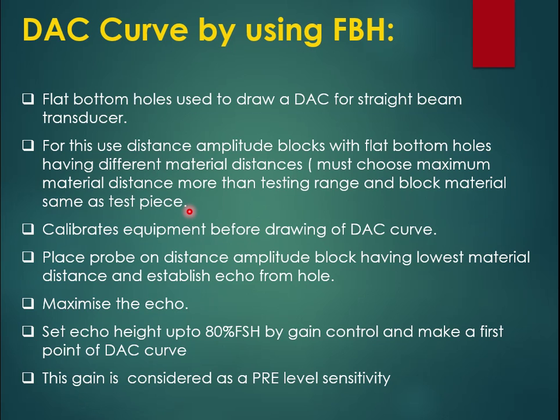For example, if you want to check steel material, then the distance amplitude blocks must also be made of the same material, steel. So you have to take the same material, and blocks of different distances up to the range covered by the related block.